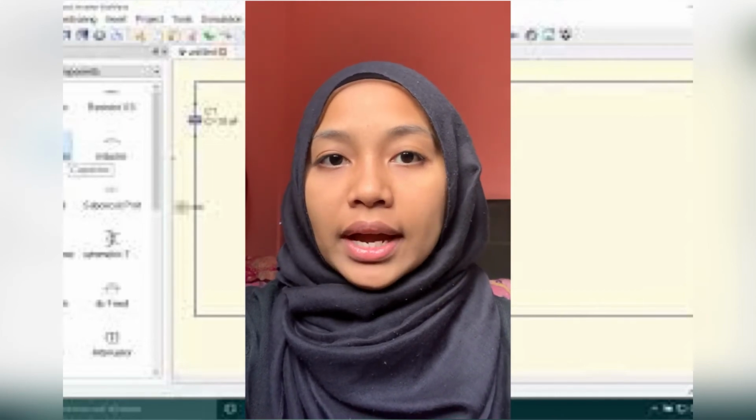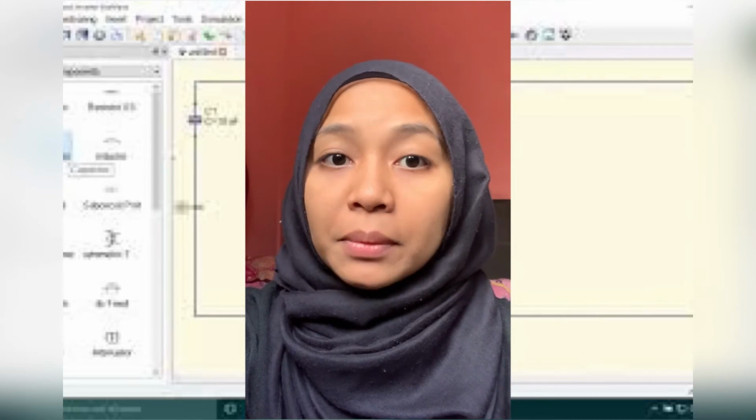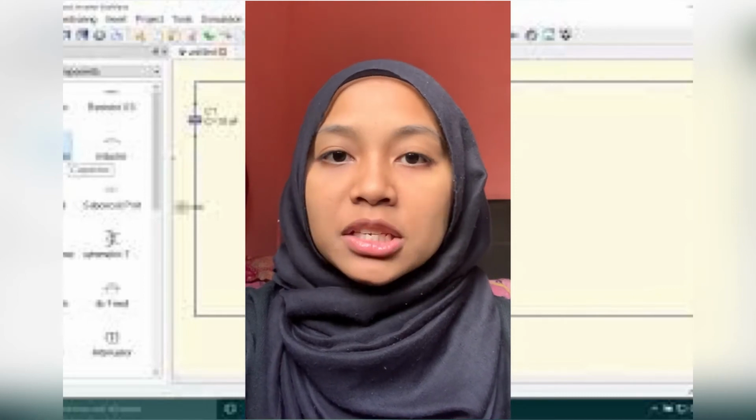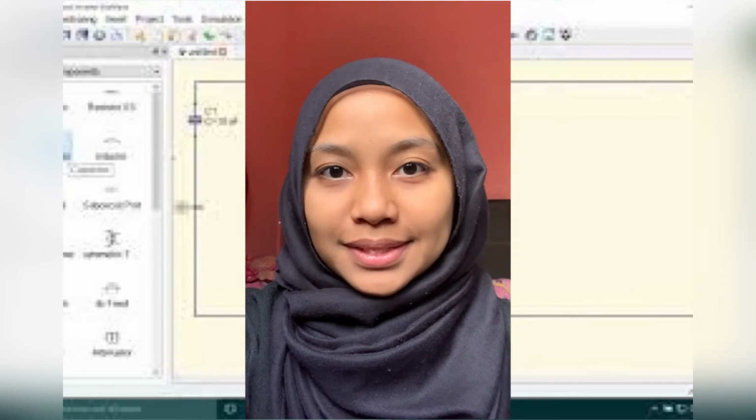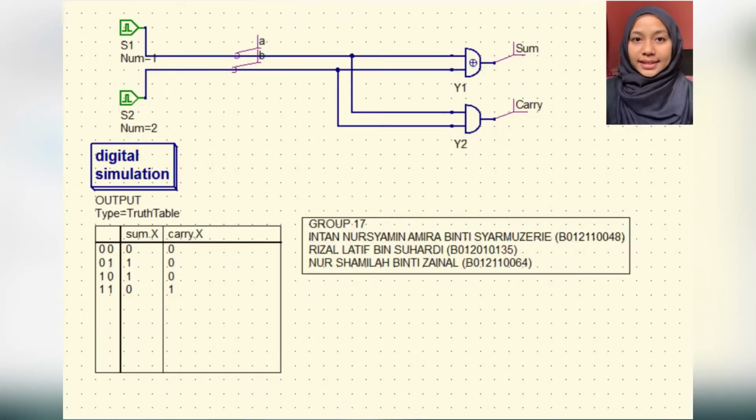It does not require any memory-like component, and it is one of the basic combinational logic circuits as present state of input variables. A logic circuit used for adding two 1-bit numbers, or simply 2-bit, is called a half-adder circuit. The circuit has two inputs and two outputs. The inputs are two 1-bit binary numbers known as augend and addend, and the outputs are sum and carry.